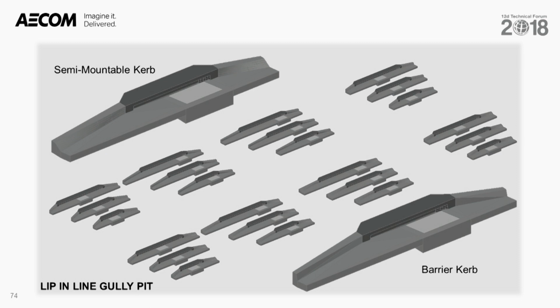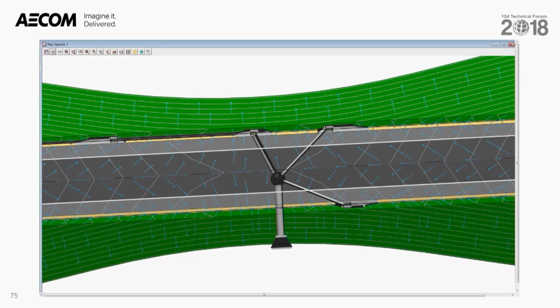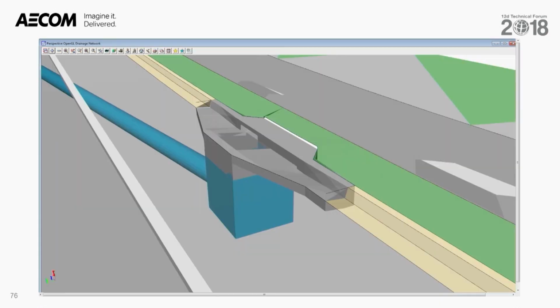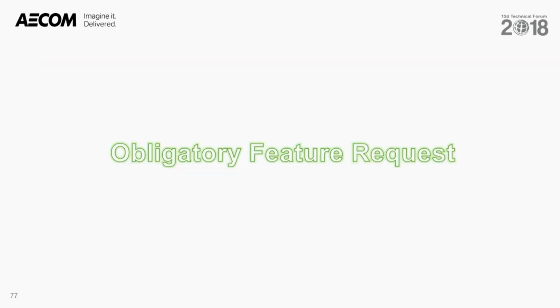The top structure of the gully pits and access chambers orientate themselves in the same way as the drainage plan PPF plots, including automatically adapting to the flow direction, so no real additional effort is required from the drainage designers who have better things to do, because the drainage trimeshes update with the standard set pit details process. And I must confess, I had to go take a quiet lie down when I realized that the drainage trimesh also tilts itself to suit the road grade calculated on the set out string, so the final 3D orientation is actually pretty close to the real thing.